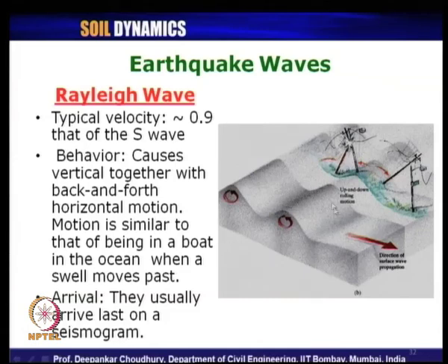And just now we have seen this kind of rolling upside down movement can occur when the wave propagates in this direction, and structures can be destroyed in this way. That is why it is said the Rayleigh wave is the most damaging one for structures constructed on the ground, not only because of its behavior of particle motion due to the wave propagation, but also, as I have mentioned, about 2/3 of the energy generated in the earthquake is released in the form of Rayleigh wave.